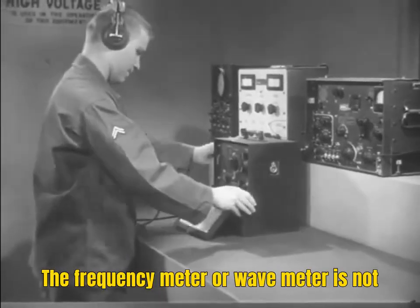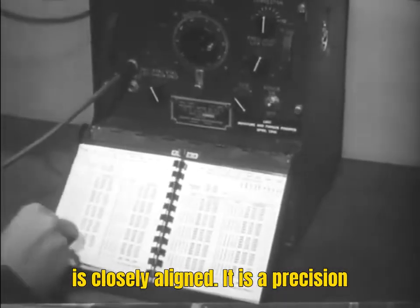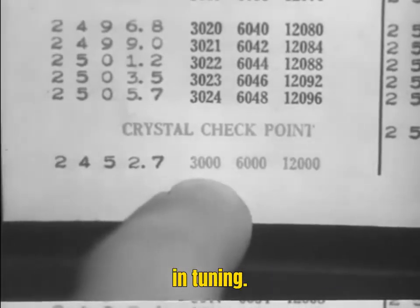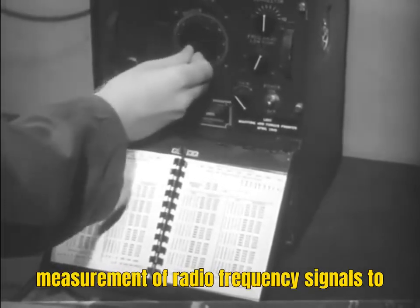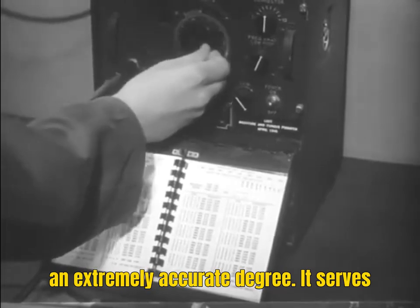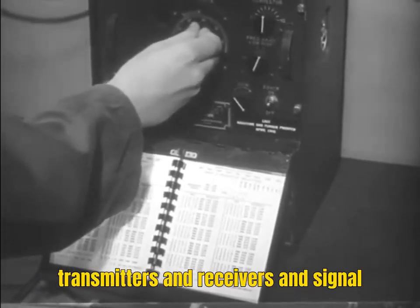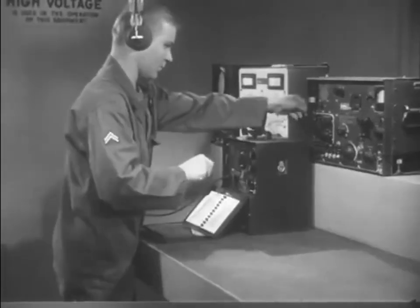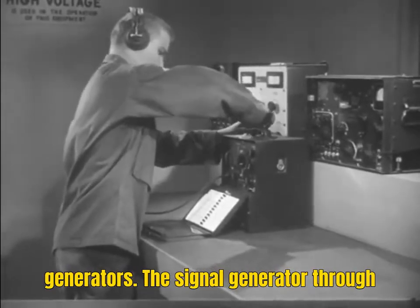The frequency meter or wave meter is not used as other signal generators, but it is closely allied. It is a precision instrument and a calibration chart is included with each set to ensure accuracy in tuning. This set is used for the generation and measurement of radio frequency signals to an extremely accurate degree. It serves also as a radio frequency standard in the tuning and calibration of radio transmitters and receivers and signal generators. The frequency meter might be called a signal generator to test signal generators.